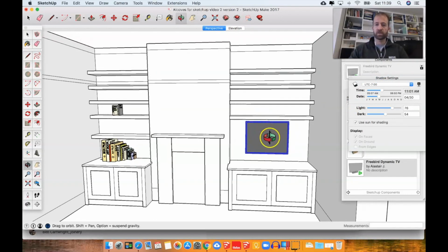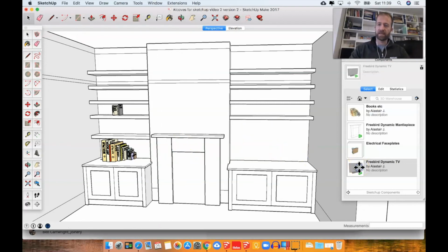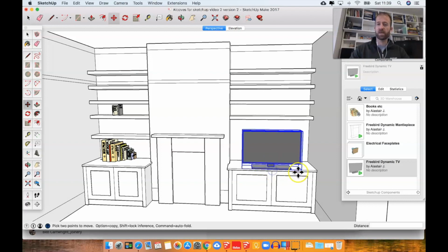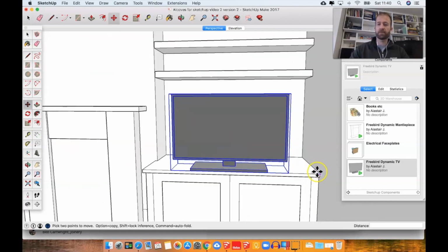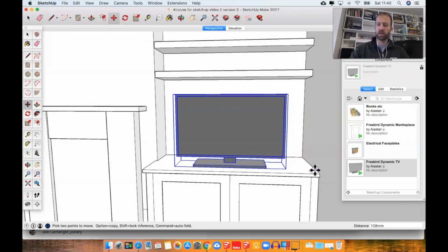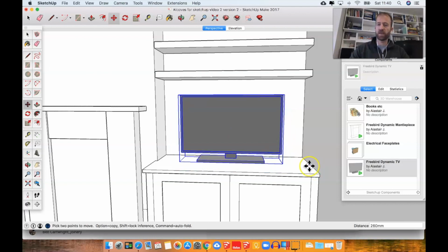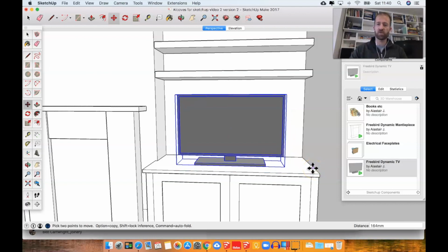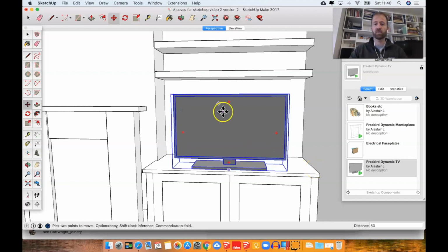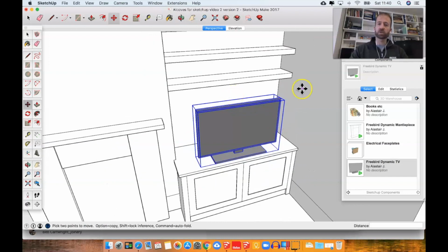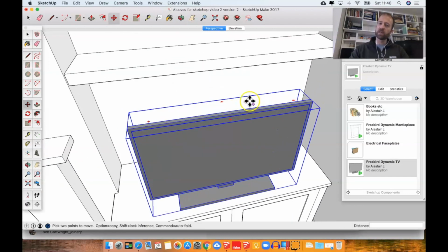Okay, so we've got this TV floating there looking a bit funny. I'll just bring the original one back in, because the original stays as it was saved. Not sure if I mentioned that has a central insert point, again for speed, so you can just quickly pop it in the middle of the unit there. You could then just use a line that goes in the direction you want to reference moving it back. That's with M for move, and then just clicking, moving back. You could type in a distance you wanted to move it back. And you could also, with the move tool, quickly rotate it.